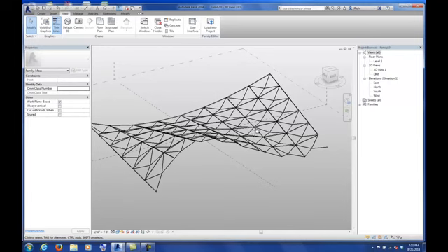What I'd like you to do is finish the space frame. For instance, I still need to turn on the rest of my pipes at the other end. Go ahead and complete the space frame. If you don't like the scale of it, for instance, this looks very little and spindly, I might want to make my spline a little bit smaller.